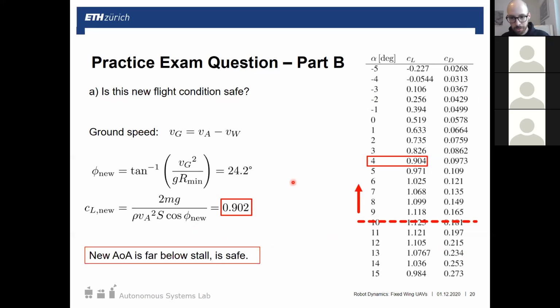So then, okay, next question here. What is CL above stall? I'm not sure what that question means, but CL, at least here for the curve we have for TechPod, just continues here. I think maybe the last thing I just mentioned about the post-stall lift curve is hopefully an answer to that question, that it normally will drop off a lot and then somehow kind of level out at some point, and then it gets a bit hard to say what happens depending on the aircraft geometry way beyond that point.